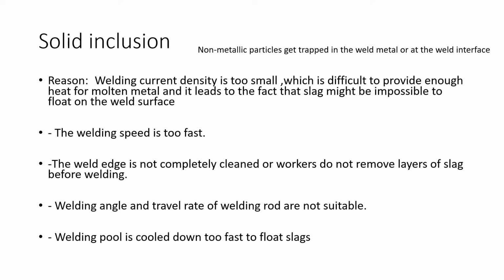Then if the welding speed is too fast, solid inclusion can also take place, because solidification will be very fast, and there is a lesser chance for floating of the entrapped slag material or other non-metals. Therefore, if the welding speed is too fast, solid inclusion possibilities are there.